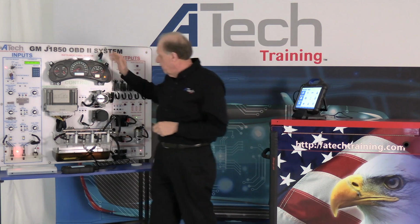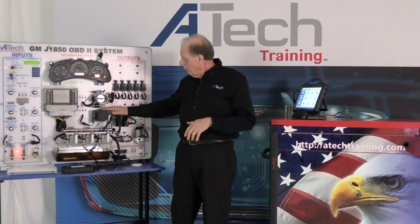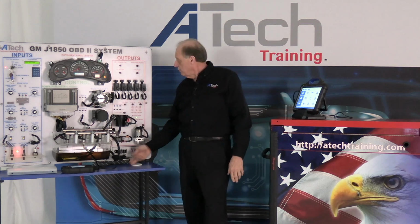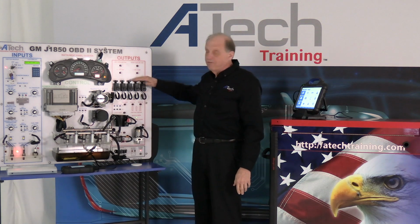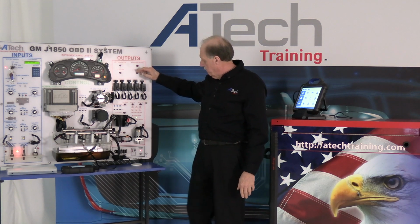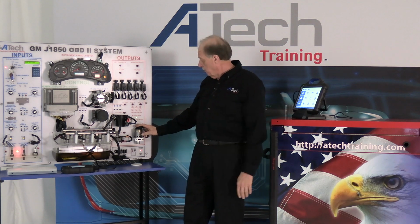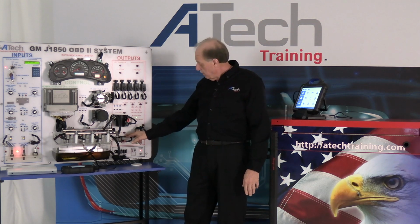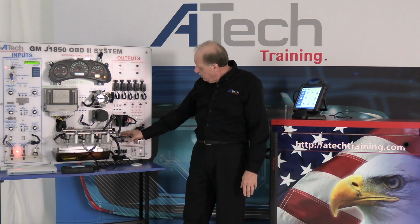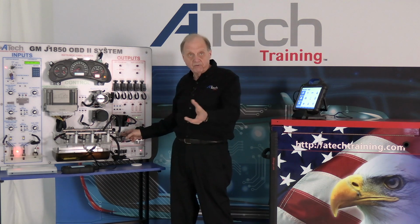So I have my ECM here. I have my throttle body, a mass airflow sensor, my diagnostic plugs down at the bottom. These are all the relays for the fans, the electric cooling fans, and the fuel pump is right here. I have an EGR, that would be an output, all right? I have my evap purge down here at the bottom. That's going to be also an output that would be duty cycled or turned straight on depending on the system.